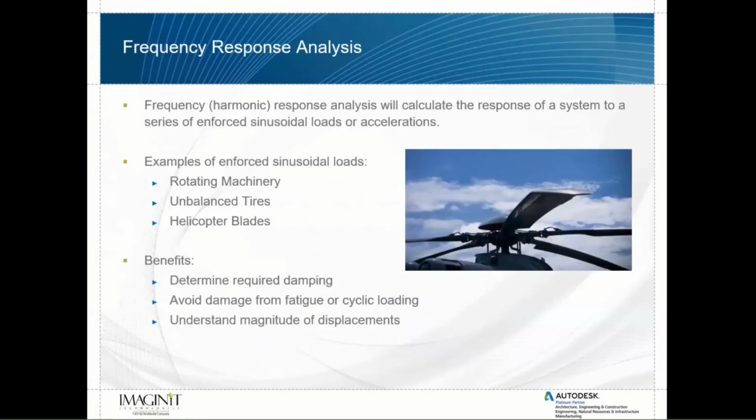So frequency response is taking it a step further. What we're doing with frequency response is we're looking at our structural response to enforced sinusoidal loads. These will typically be accelerations. So for instance, you can have things like rotating machinery, unbalanced tires, helicopter blades. All of these will produce a sinusoidal load function that looks like this. So you have that sinusoidal load input coming in. Based off the frequency, that sinusoidal load will look different. However, all of these types of situations can create that type of input.